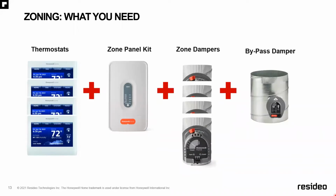Okay, so I know that some of our competitors will use a master thermostat with various sensors, but we are basically going to have a thermostat in the loop at every zone. So we're going to combine that with a zone panel and the respective zone dampers, as well as the bypass damper that will deal with the excessive air that'll come when just a few zones, or a smaller zone, is all that is calling.